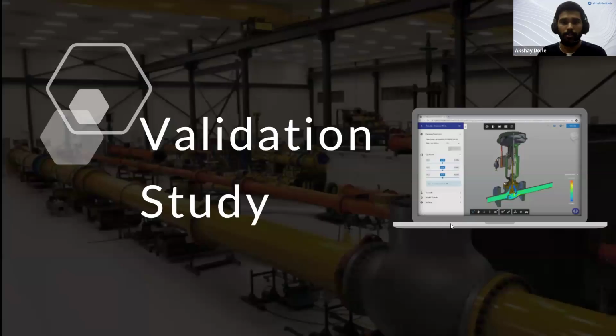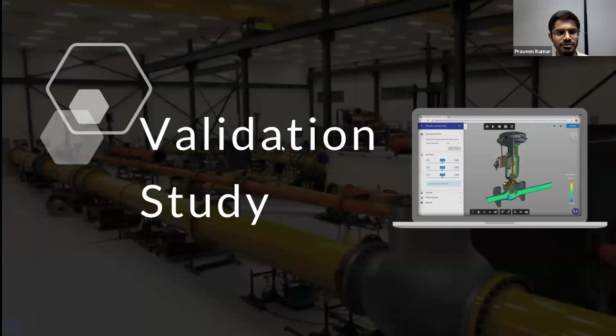So moving on to the validation study, I would like Praveen to share. Yes, I'll share. While I'm sharing the screen, extending the point of Akshay: yes, CV is slightly compromised when we go for avoiding cavitation, and that's where CFD comes very handy. These tools help you optimize the flow path to balance flow capacity as well as avoid pressure drops.